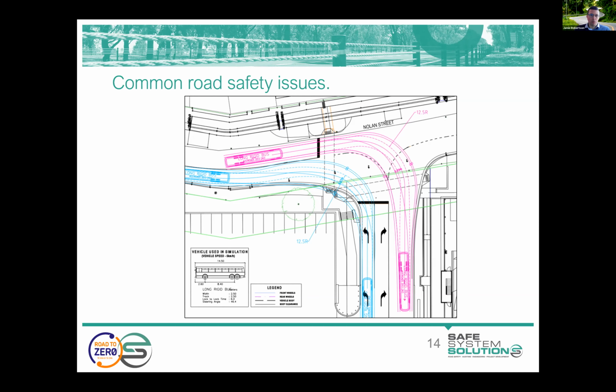We will often plot an additional line, a parallel line to the body of the vehicle, and you can see here on either side 2 parallel lines. That's a 1/2 metre clearance line on either side of the vehicle as required by Austroads, which should be provided to roadside furniture, to curbs and so on.